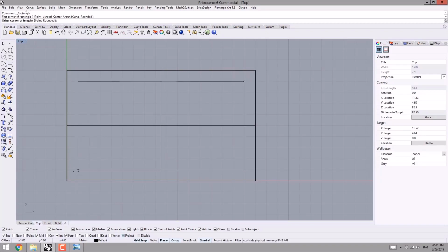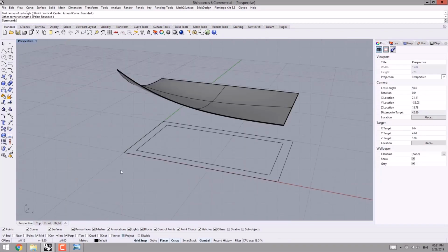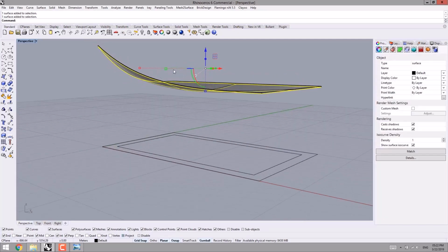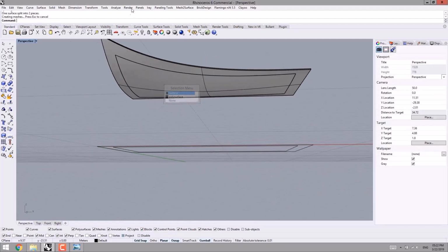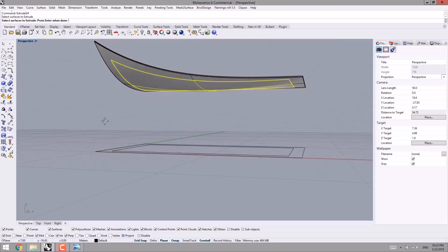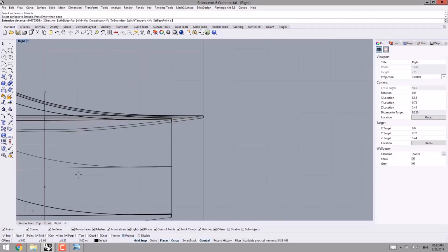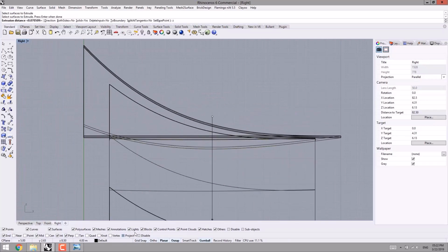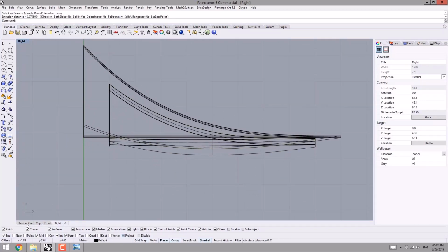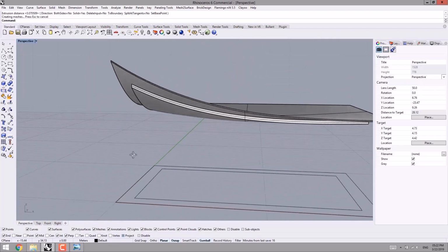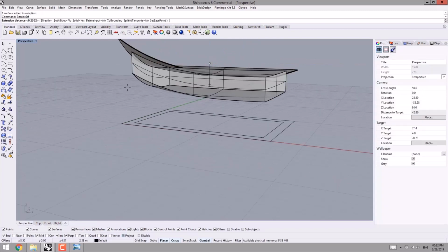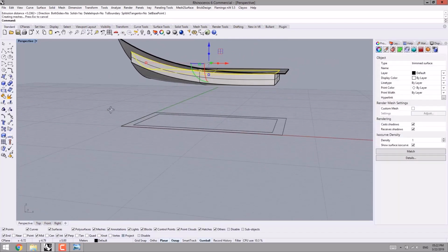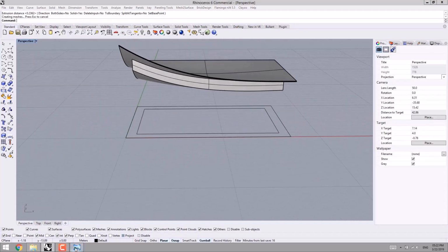Then one more rectangle, but smaller in size. Then I want to select the bottom surface or the bottom curve. I split it. Check this out. I have set the rectangle as the cutting object. I start extrude. Then I want to extrude the split part to create the stair-like surfaces. Check this out, which has been extruded from inside the surface. However, we can maximize the distance of the extrusion. So I select it, then I extend it. Well done. This way.